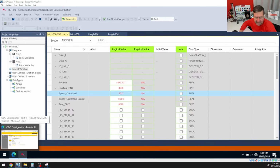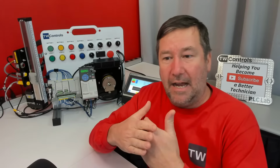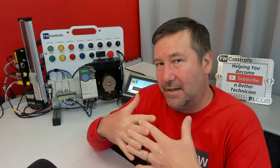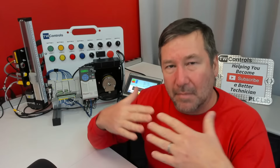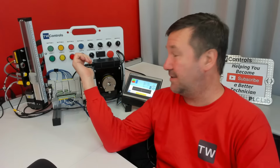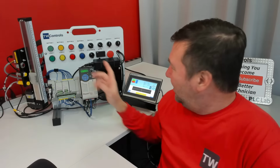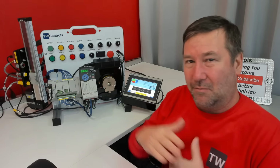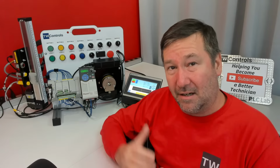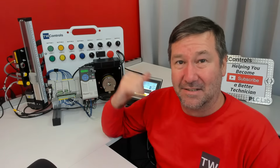Okay, now that still is not good enough for our PID. And I think a lot of us get stuck right here because most of your exercises on PIDs are showing an analog in and analog out. Well, in this case, we have an Ethernet out, but we managed to work that one out. But here, we're getting just a continuous measurement, but we need the rate of this thing. How fast is it turning?